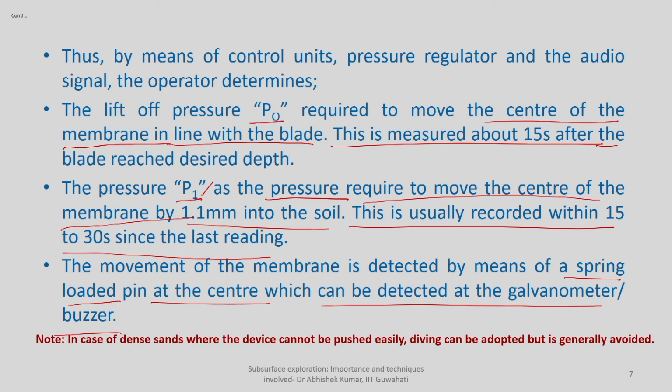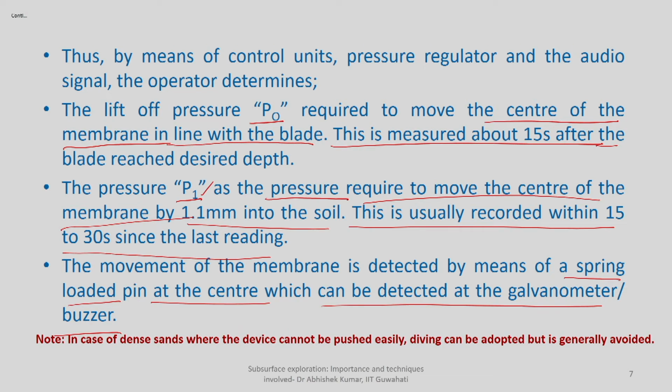Okay, there is a note here. In case of dense sand, where the device cannot be pushed easily, like continuous lowering cannot be done, driving can also be adopted, but it is generally avoided because it can cause some kind of damage to the membrane and to the blade itself. So it can be done, but if the impact load is too high, then it can cause damage.